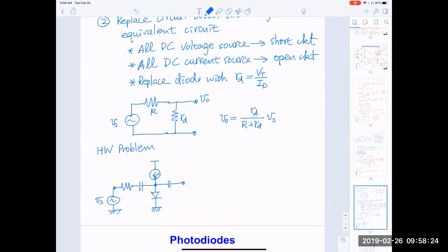And here is the power supply voltage, which we typically call VDD. The name will become apparent later. And for example, if this is the V out, you can practice the previous rules, first transforming this into an AC equivalent circuit. This particular circuit is kind of trivial DC-wise. We are biased with a current source, ID, so there's no need to solve the DC problem. The DC problem is trivial. Diode current is ID, and you can simply write the small signal equivalent circuit.